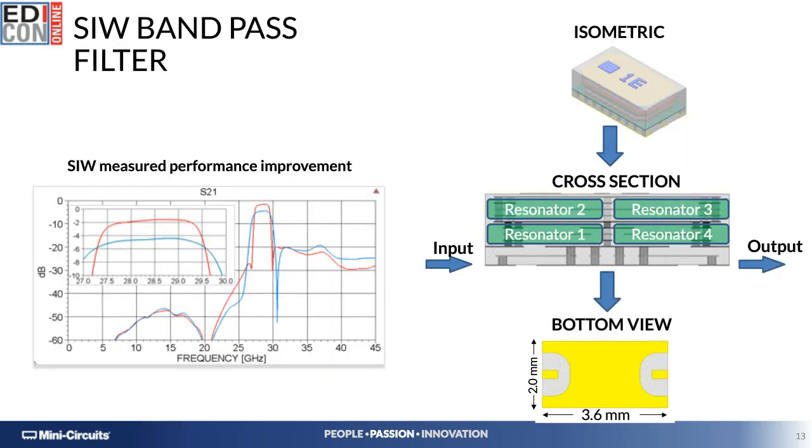We have also realized implementations of substrate integrated waveguide filters. What we're seeing today here at this slide are test measured results on two kinds of spins for the same actual topology. The blue plot shows the standard technological implementation on LTCC for this particular substrate integrated waveguide filter.